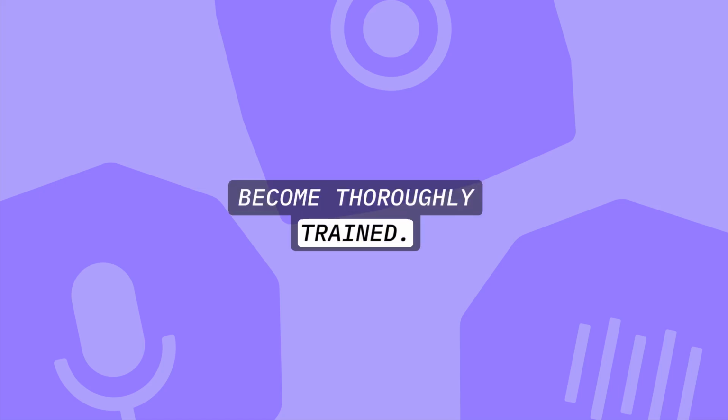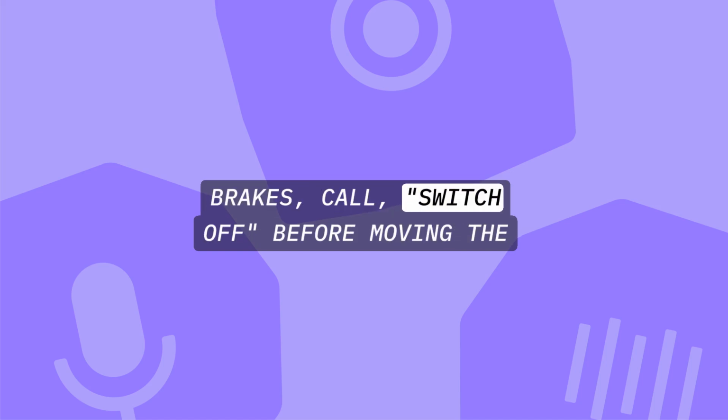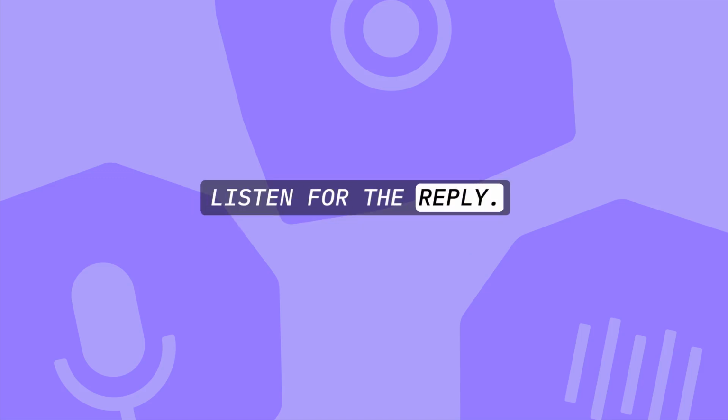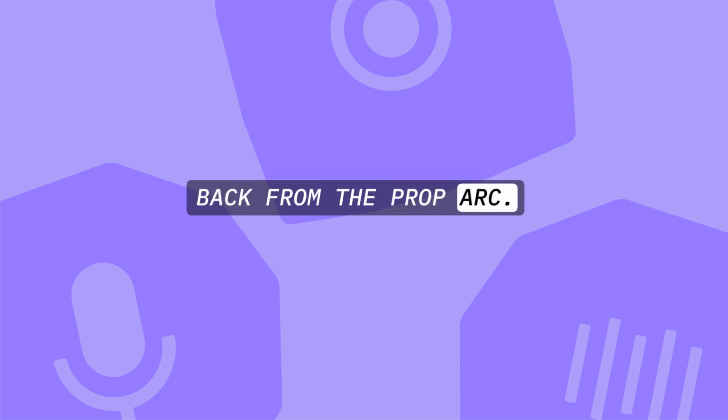What safety procedures must be observed when hand propping a small aircraft engine? Become thoroughly trained. Have a qualified person in the cockpit check the brakes, call, switch off before moving the prop, and make sure you have solid footing. When ready to start, call contact and listen for the reply.